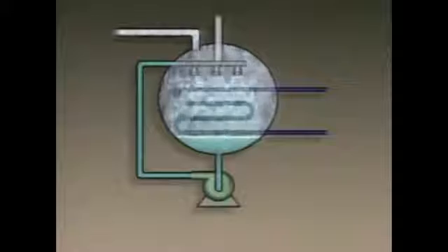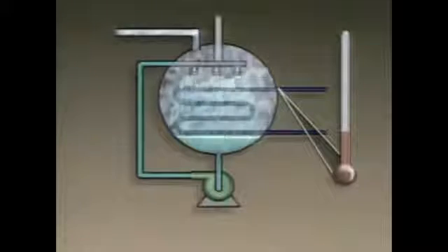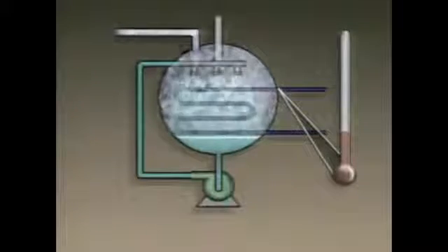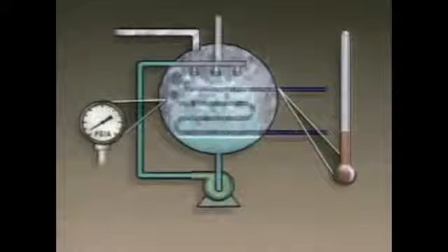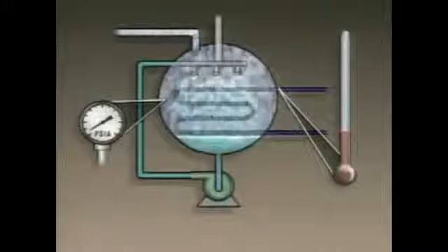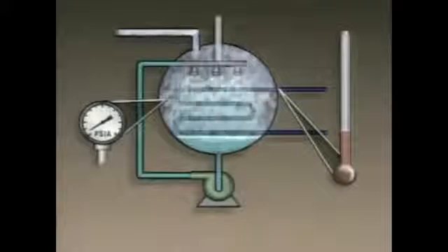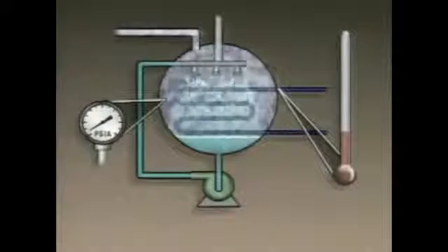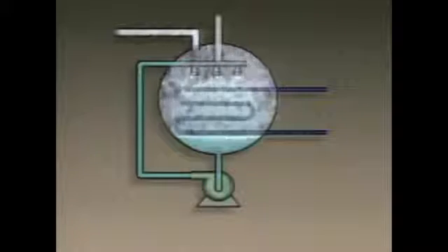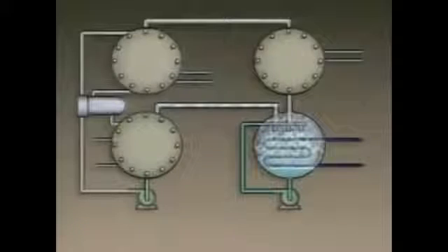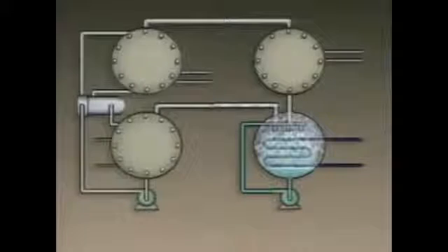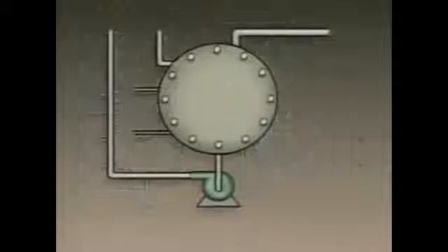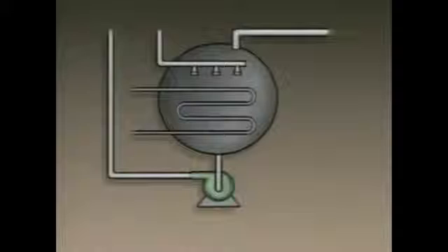The temperature of the chilled water is typically too low to vaporize the refrigerant at atmospheric pressure. This system operates at a very low pressure to allow the refrigerant to vaporize at low temperatures. In our example, the pressure is around 0.15 psia. At this pressure, the refrigerant will vaporize at 45 degrees Fahrenheit. The low pressure that's needed is achieved by using a chemical absorbent such as lithium bromide.